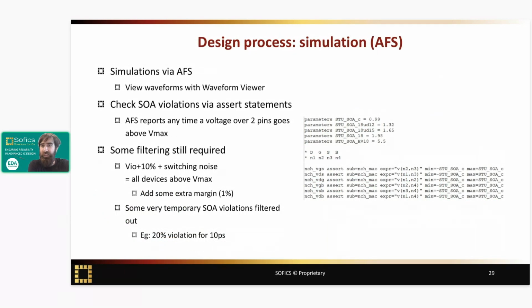The simulation happens with AFS, and we view the results in the waveform viewer of EDA Solutions. The main extra bit on the overvoltage tolerant case is that we check the SOA violations with assert statements. What this does is that the simulator flags if anytime a voltage goes over the maximum allowed voltage, or in other words, if we have a SOA violation.